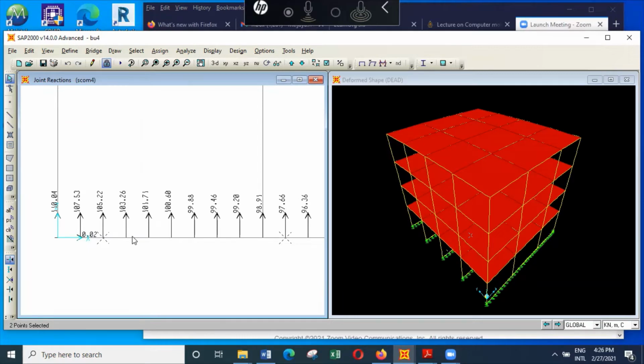But when you allow for the weight of the foundation, we found that the net bearing capacity is 107, whereas here you get something like 107 divided by 1.8 divided by 0.5, so you get 118, which means the bearing capacity has been exceeded in these areas.